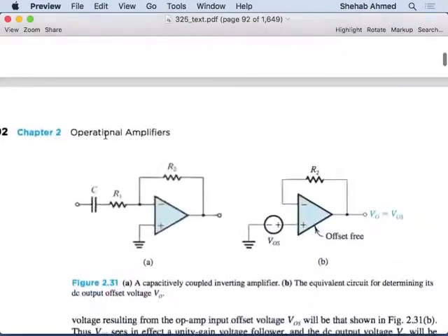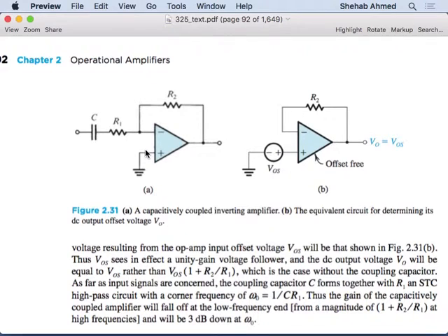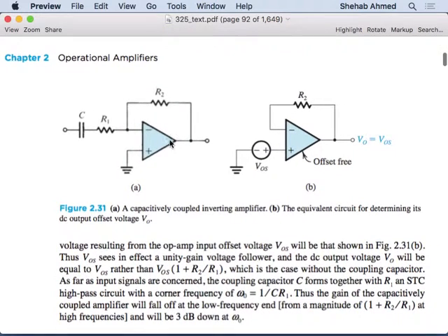So we found that this capacitively coupled amplifier deals nicely with the offset voltage problem because I can pass my signal through and amplify it with whatever gain I would like to control, right? And I have to live with having some offset voltage, even though I trimmed it and nullified it. But I'm not at least magnifying it, right? So that's the benefit of this capacitively coupled amplifier.